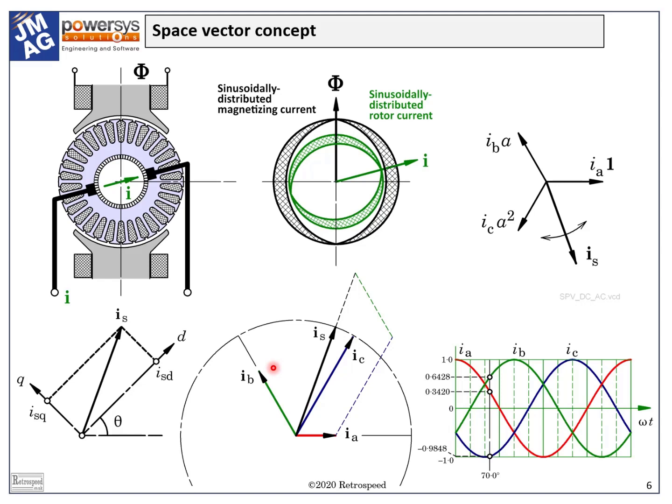When the three-phase currents follow a sinusoidal pattern, as they do in steady-state operation, it turns out that Is is fixed in magnitude and rotates steadily at synchronous speed. Now here we have the very essence of the operation of the AC machine, at least in terms of one of its variables, the current, or more precisely the fundamental space harmonic of the ampere conductor distribution, current for short.